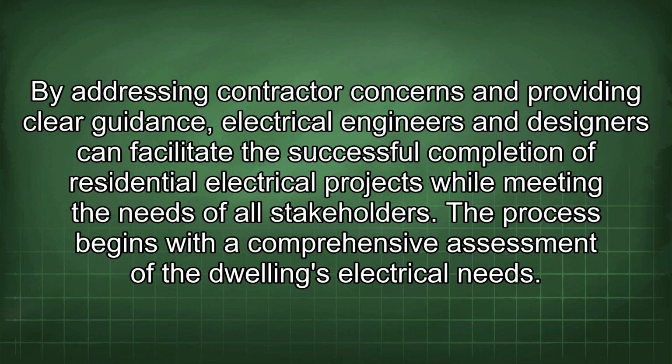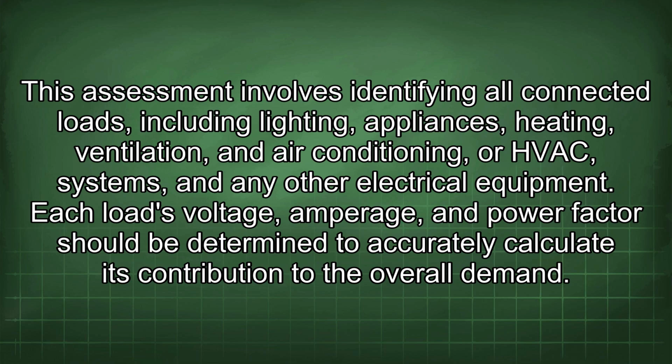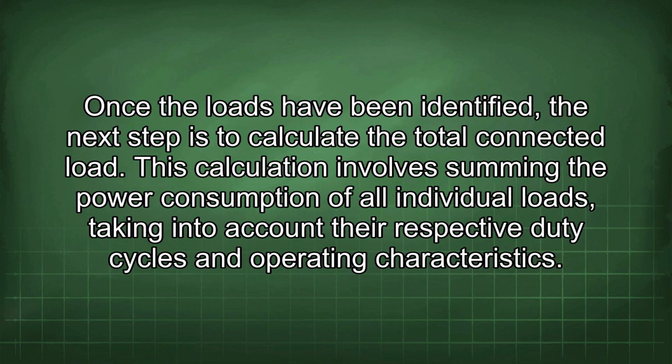The process begins with a comprehensive assessment of the dwelling's electrical needs. This assessment involves identifying all connected loads, including lighting, appliances, heating, ventilation, and air conditioning or HVAC systems, and any other electrical equipment. Each load's voltage, amperage, and power factor should be determined to accurately calculate its contribution to the overall demand.